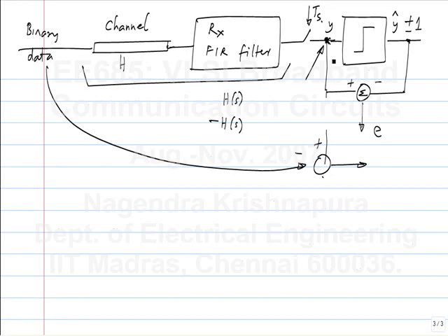Okay, still not convincing. So let's take a PRBS pattern which has all possible 7-bit patterns. Let's say it's a PRBS 7, and then after doing adaptation, I have not even said what adaptation is, but after doing it, I will get all zeros. That means that for any possible 7-bit pattern, the ISI has been cancelled because of the filter. Now, at the very least, if the ISI is less than 7 bits long, for any other possible pattern also it is cancelled out, isn't it? Is that okay or not?